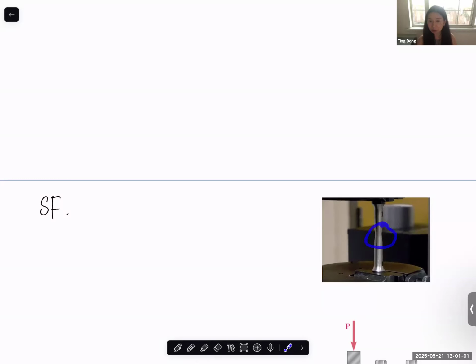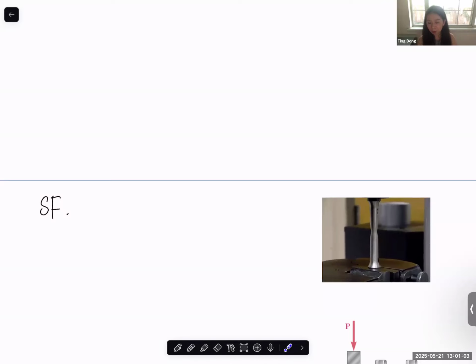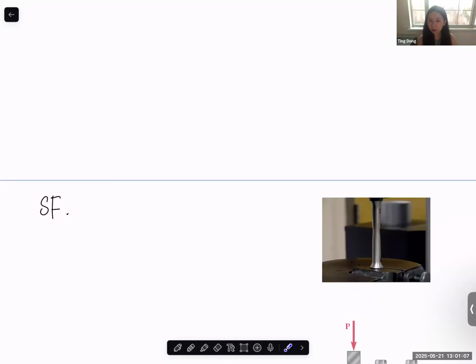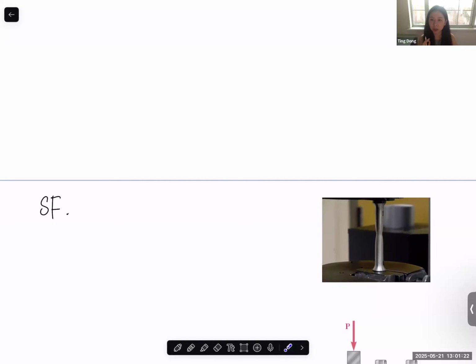And the stress that causes the actual break of the material is the breaking strength, which, because of the necking, is lower than the ultimate strength. Before the breaking, the maximum stress generated in the structure is the ultimate strength. So these are the data we get from the lab when we have a specimen and do the test.